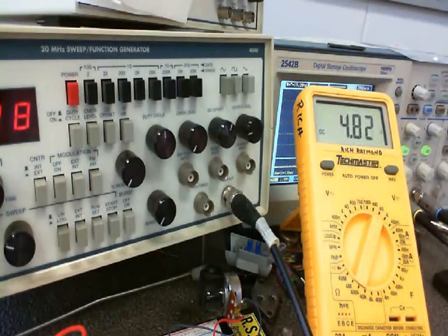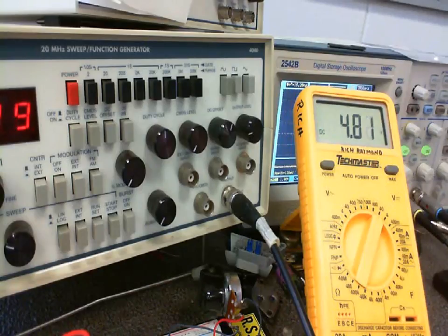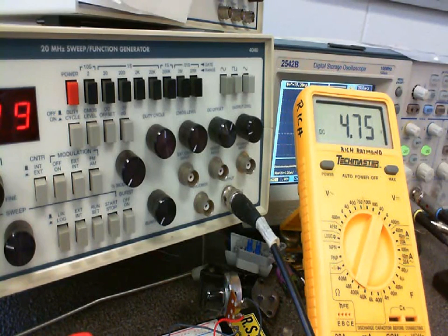So that's 4.8 volts. If this voltage starts dropping down, that's because the voltage drop across my collector resistor is going up, right? If the voltage drop across the collector resistor is going up, the only way it could be going up is IC is going up. And IC is controlled by beta. So you can see it starting to do what?